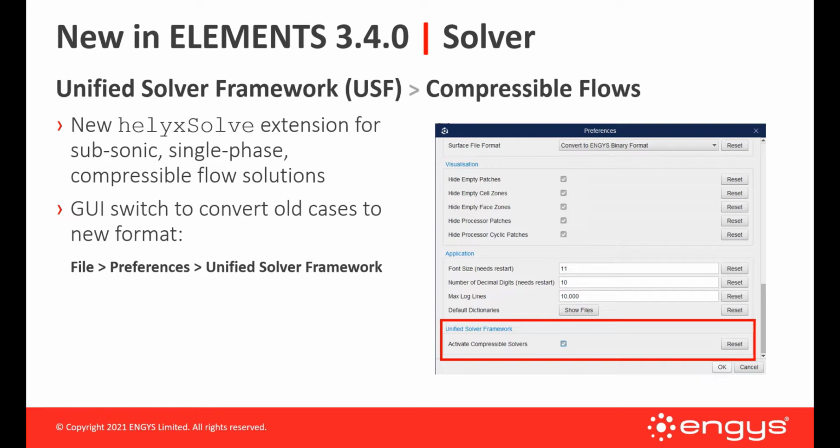We have also introduced support for the compressible flow solutions in the USF framework inside the graphical user interface. So it's possible to convert all cases to the new USF format by changing the preferences under File, Preferences, Unified Solver Framework, as you can see here.